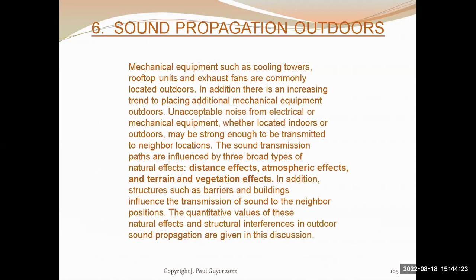Other techniques, double wall construction. The gypboard on the noisy room side is not attached to the same studs as on the quiet side, so you have broken that sound transmission path through the solid elements in the wall. Staggered studs is another approach, and the distinction between the double stud and the staggered studs is that with staggered studs the studs are on common plates and bases, and so the sound path is not broken as definitively as it is with a double stud wall construction where the studs are on separate plates and bases.